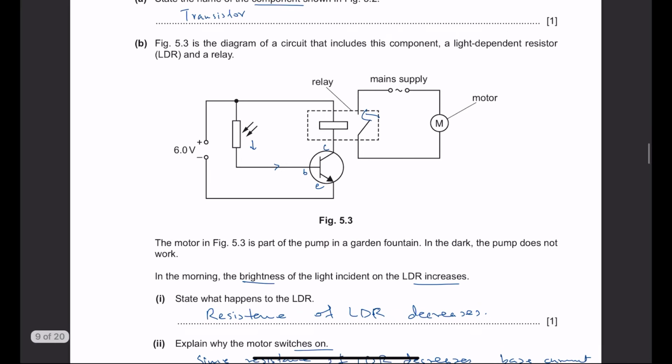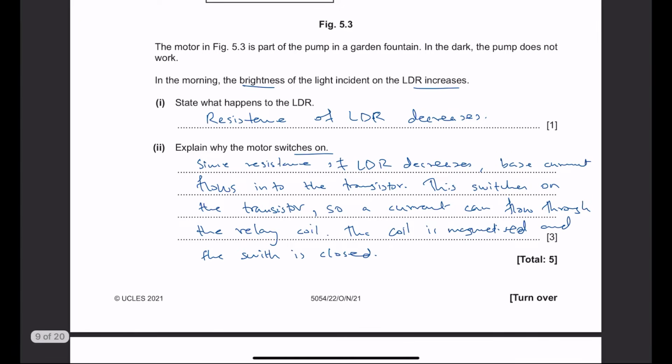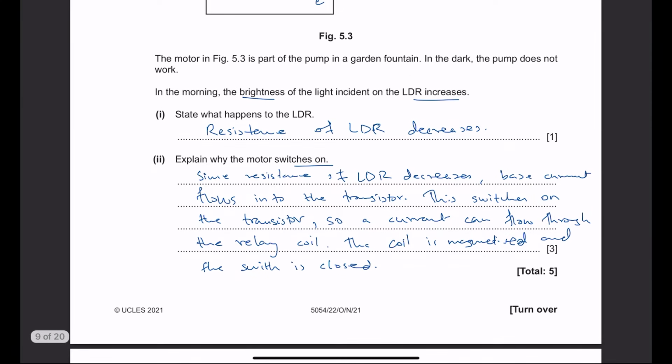So now what happens is, if this switch closes, you have this circuit which is complete. Therefore, a current can flow through the motor and the motor will get powered from this mains supply. It is important to note that no current flows from the cell to the motor. The cell is not powerful enough to run the motor. The motor is probably connected to a 220 volts mains supply. This switch just closes and now this path is complete. A current will flow like this in the motor. Alright. So the coil magnetizes and the switch is closed.